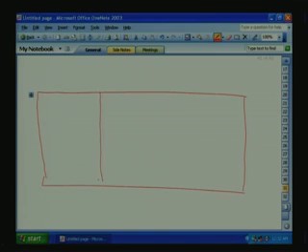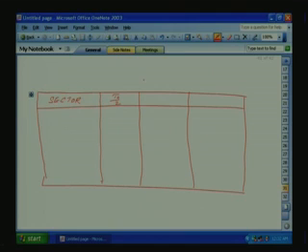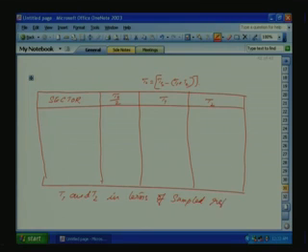This is the sector information, then T0 by 2, then T1 and T2. Once T1, T2 is found out, T0 is equal to TS minus T1 plus T2. From there, we can find out T0. Why is T0 by 2 required? We are splitting T0 into halves, at the start and end with equal duration, and the active vectors are placed in the middle. So, this table gives T1 and T2 in terms of the sampled reference phase amplitude.